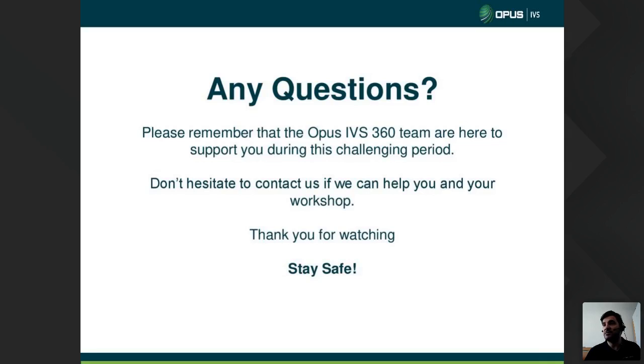David Everson has asked, can you explain the 2 DPF loads in percentage? The percentages for the DPFs we never rely on. When it comes to DPF diagnosing, we don't use the percentages because they don't often mean what it actually is about the DPF condition. What we rely on is the DPF pressures, where they tell us what the condition of the DPF in itself is, and of course the testing of the pressure sensor to confirm that the DPF pressure really is that high, or whether the sensor is reading incorrectly.